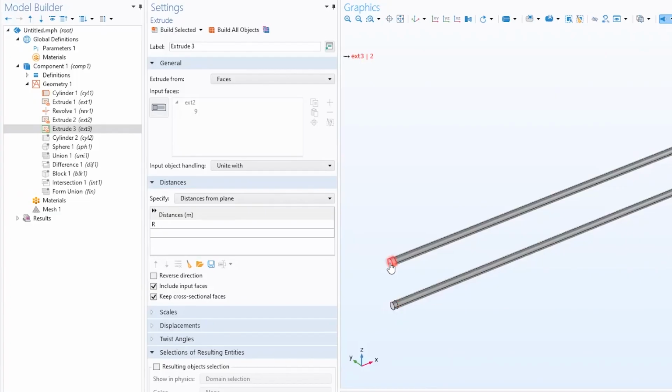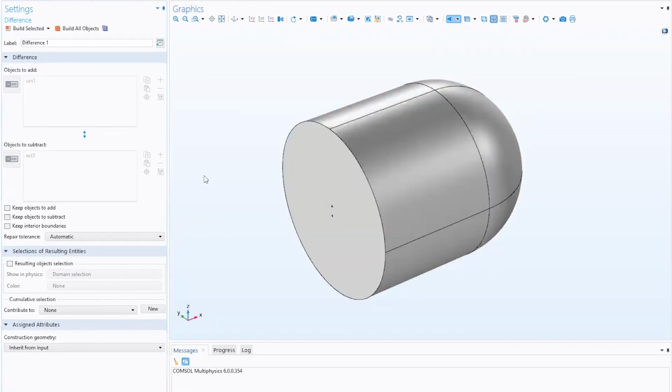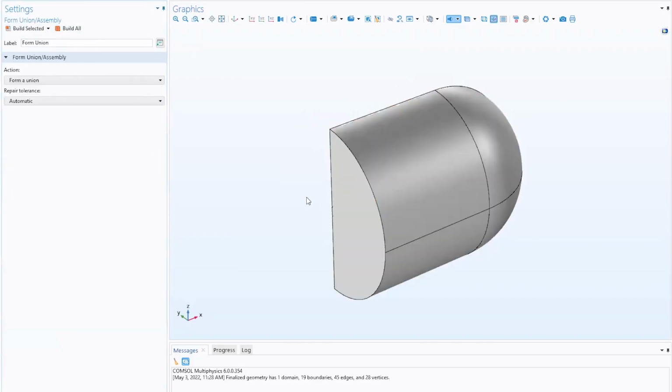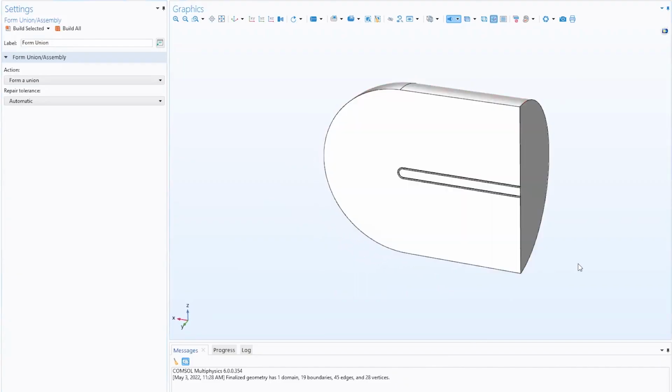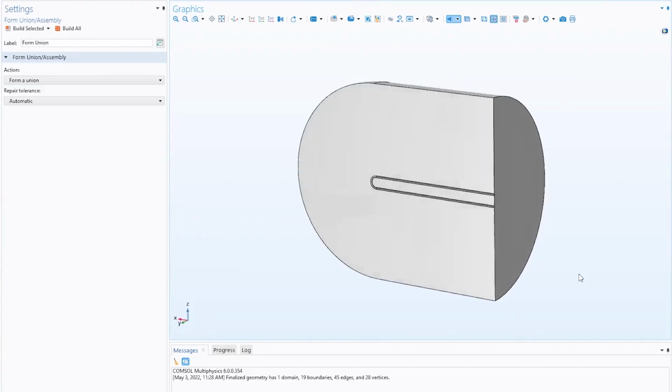We have a couple of domains representing the source, the battery and the switch, and the sensor, the light bulb. And then we have all the other domains as well. And then we have a set of other geometry primitives here. And what we'll do is we build all those up together to represent the space around. And then we're going to cut that all in half such that we have our 1/4 symmetry model of the entire structure that we're going to work with.